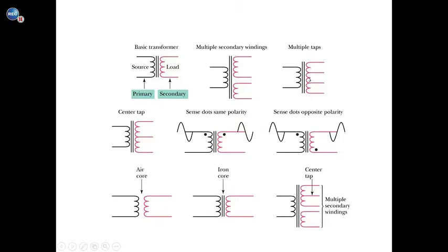This is essentially like having multiple inductors in series with one another. When we have inductors in series, they divide the voltage the same way that resistors do. A lot of transformers have just a single center tap, and so the voltage from the center tap to one of the main leads is half of what it is from the main lead to the other main lead. So the center tap voltage is usually half of the full secondary voltage.